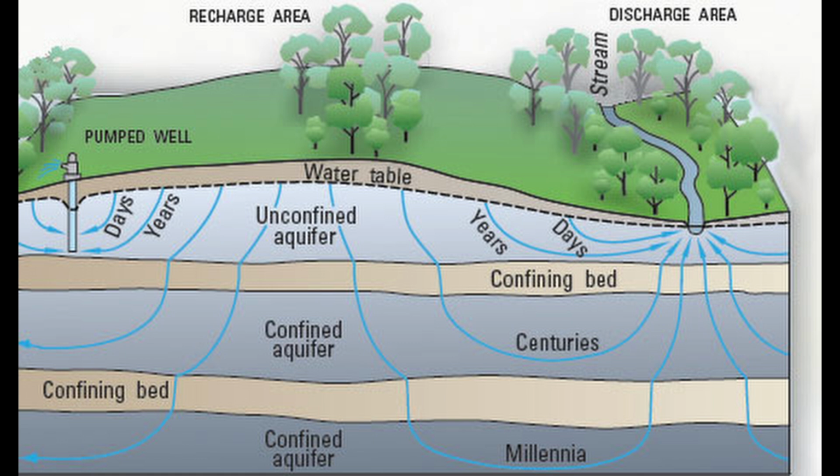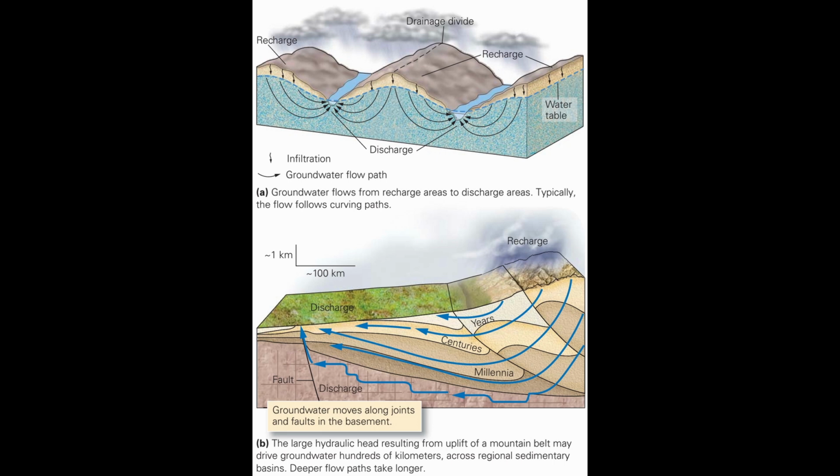What is important to recognize is that water is flowing underground at various elevations below the surface, and that the groundwater dam you're building will restore the elevation of the uppermost water table. Think of how when you drill a well, the well taps water in a deep layer of groundwater that is far below the surface. The groundwater dam only affects the uppermost layer of groundwater.